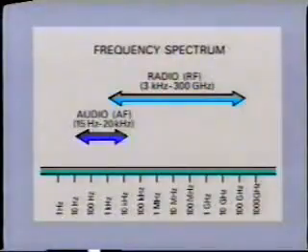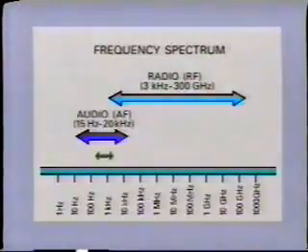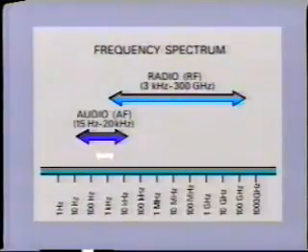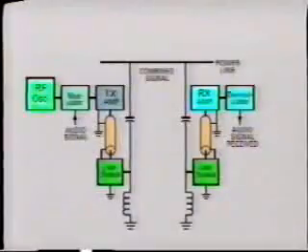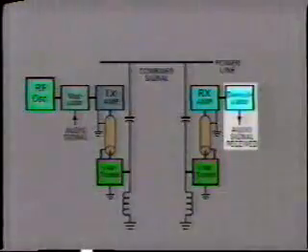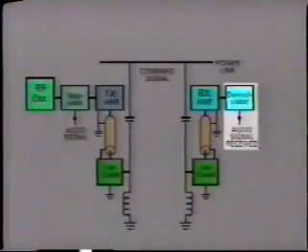Signals such as voice and telemetry all operate within the audio frequency band, usually between 300 hertz to 3,000 hertz, or 0.3 to 3 kilohertz in relation to the carrier signal. This audio signal is mixed with the RF carrier signal in a modulator before transmission down the line. The mixed signal is then demodulated in the receiver at the other end, leaving only the audio signal.